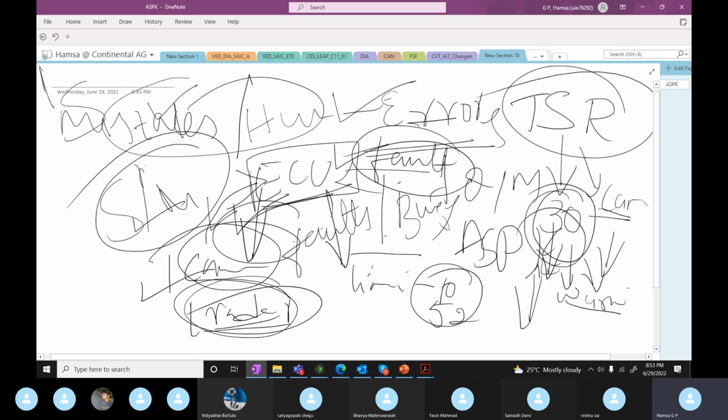Where there is no input to the ECU from the camera, the ECU will wait for the time mentioned by the developer. It could be 2 seconds, 5 seconds. Based on the requirement, the developer configures this time. So if the ECU is not getting the camera input for 5 seconds, it will set a fault that it is not getting input from the camera.